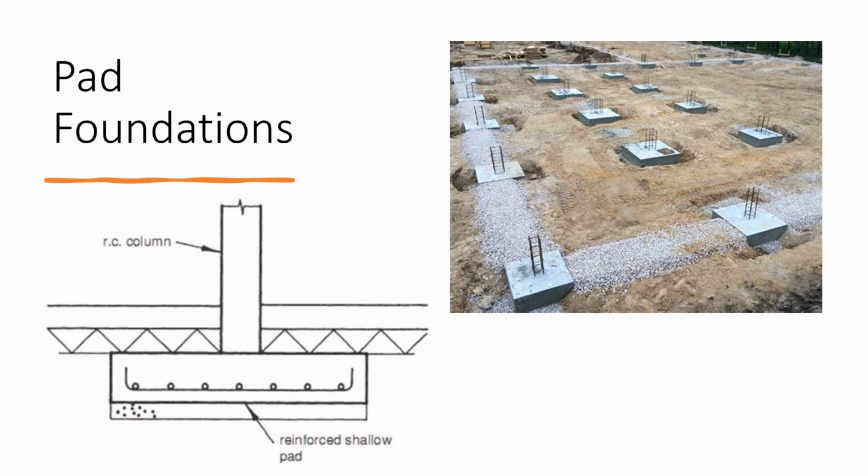The angle of spreading is determined based on the bearing capacity of the underlying soil and the concrete strength. The size of the pad must be such that tension is prevented within the concrete so that no cracking will result in failure. The ability to resist the punching shear is a governing criterion that determines the depth of reinforced concrete pad foundations.